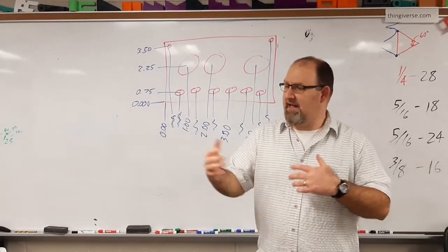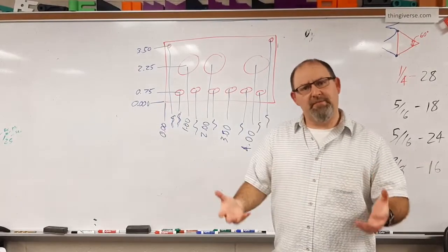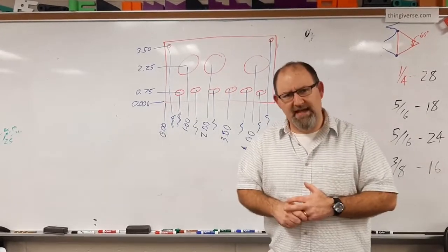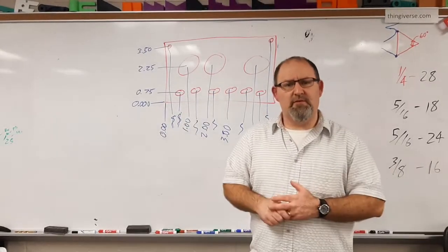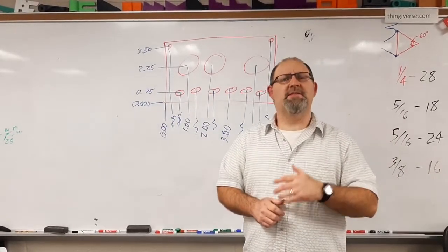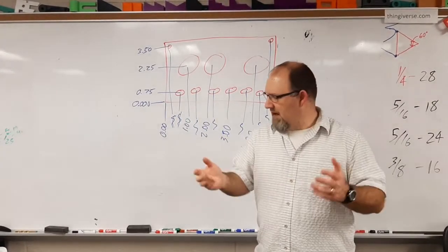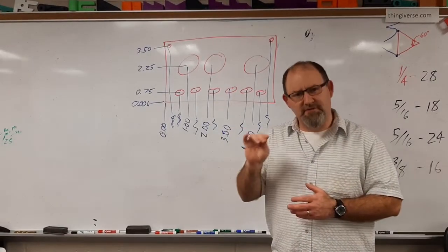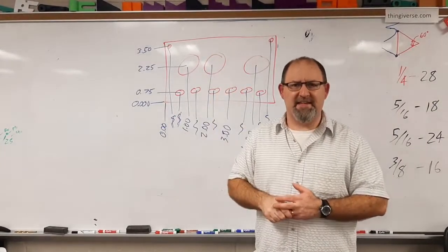If you're at a place that can have a lot of loose tolerances, something like a welding or metal fab type shop, maybe an HVAC shop where the ductwork has a bit of play and you're fabbing out ductwork or what have you, in those cases you might be able to run with much looser tolerances. And of course, the looser the tolerances, generally the cheaper the cost, because it's a quicker, easier process. You don't have to have as much advanced machinery if you don't have to get super tight or super fine on tolerances.